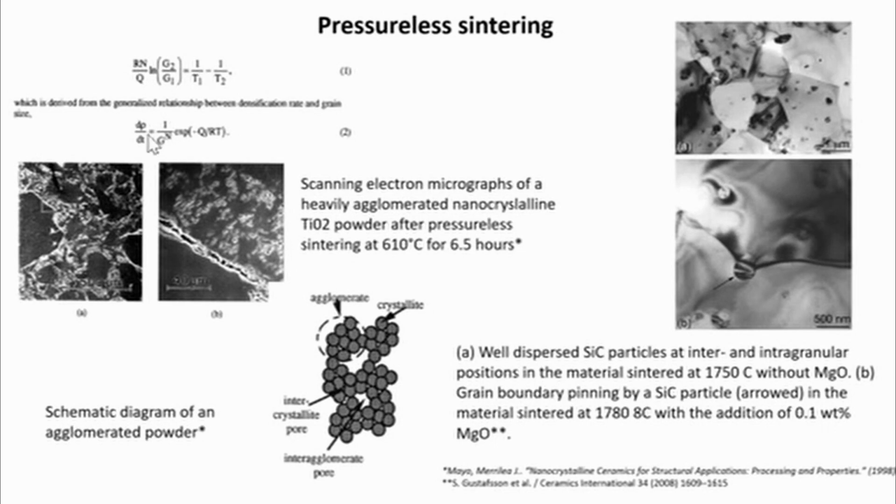size of 10 nanometers and a green density around 46% of theoretical. Here you can see big intergranular pores. An agglomerate can be defined as a bonded mass of grouped particles, and agglomerated powder contains many such masses. When an agglomerated powder is compacted, the hard agglomerates pack together rigidly and tightly, leaving behind pores on the scale of the agglomerate size.